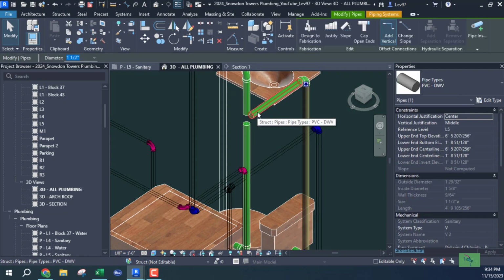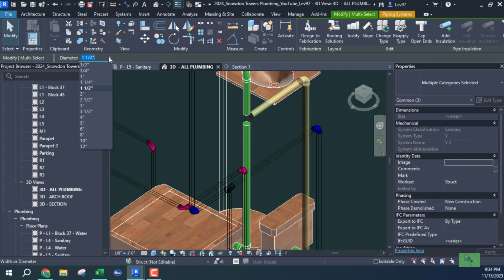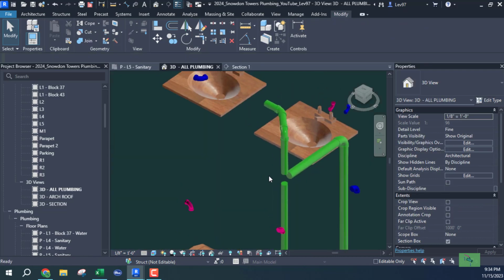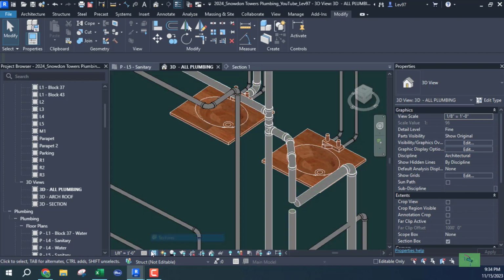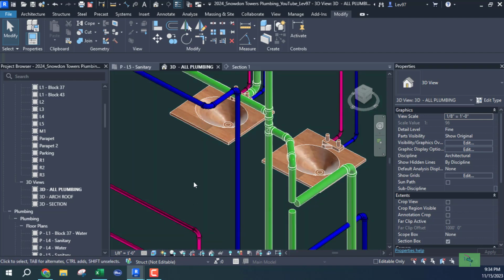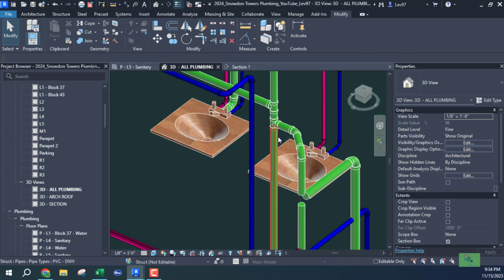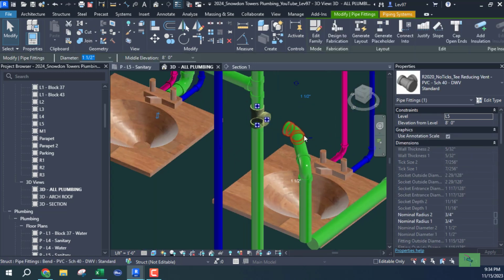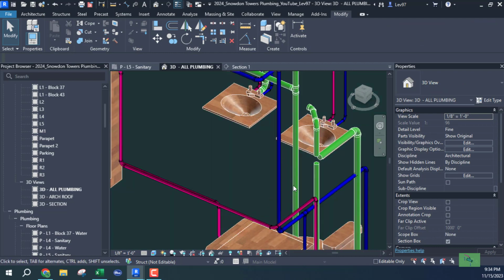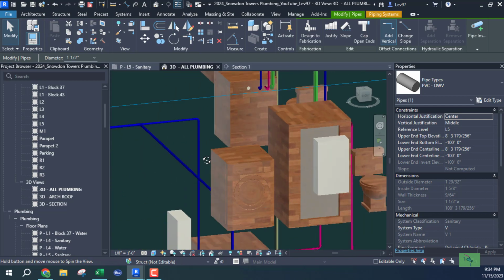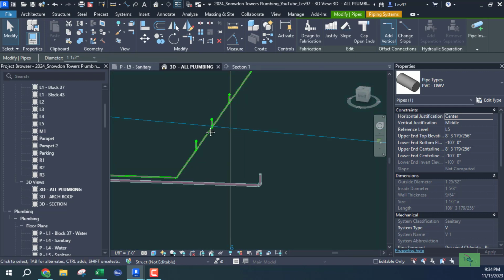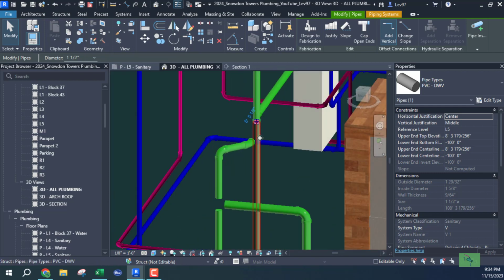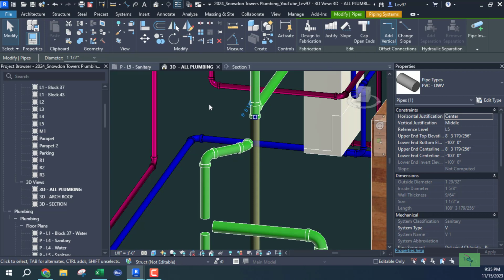Okay. Tab, changing that to a 2-inch. Okay. And this is all going to be 2 inches. Let's reset this display. So that's a 1.5 inch. Let's erase this guy. Come back and erase again. This is, what size is that? 1.5. Okay, that should be a 2-inch. Let's go all the way down and see if any connections are being made. And there went all the way down underground somewhere. But the reason that's long like that is because I want to go through the entire building. That's my vent riser, so that's why that's all the way down.